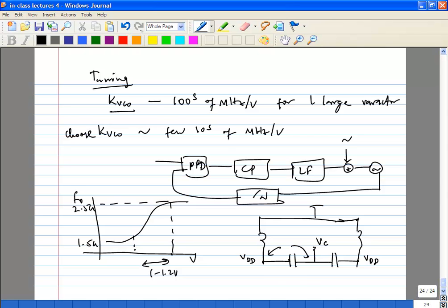If you have a very large thermal noise in and around DC at the outputs, these two varactors are going to convert it to phase noise, because the capacitance varies as a function of this voltage. Capacitance varies, the frequency will vary. What does frequency variation with noise mean? It just means the noise sidebands around your VCO center frequency. So if you have a very large KVCO, the gain for AM noise from this point to the phase noise sideband is going to be very high.